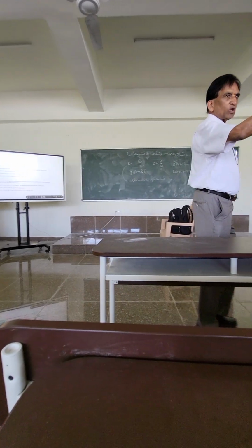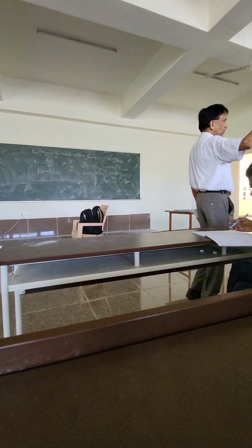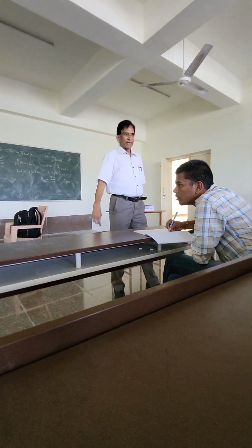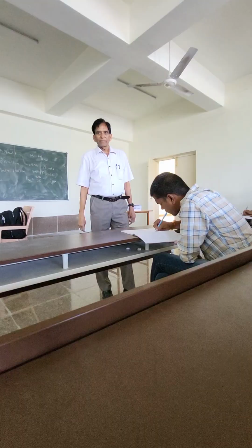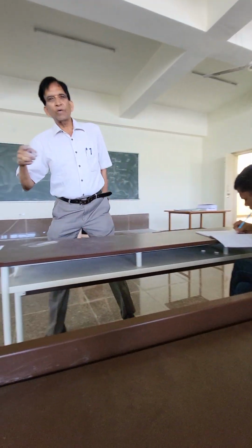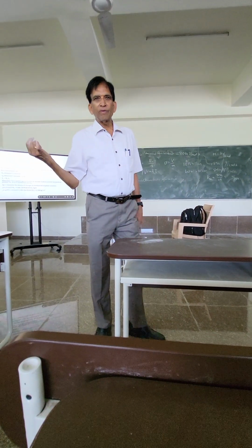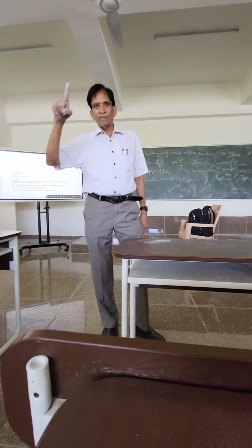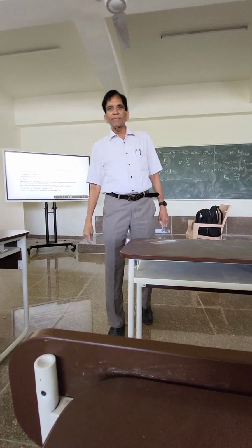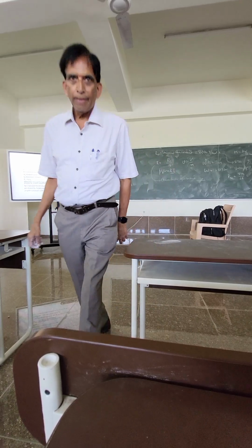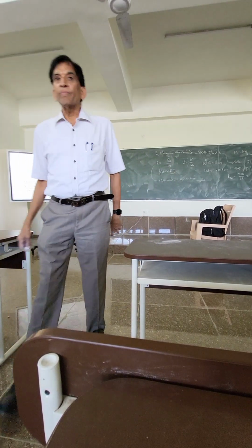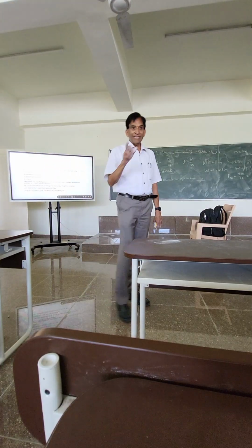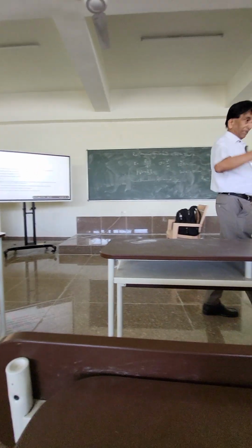That is the number you would have used in your Grashof number, with rho squared, in your lab. Forced convection experiments also require the density of air, for the calculation of Reynolds number, which is V d rho by mu. People who have done this experiment would have done the calculation of rho.